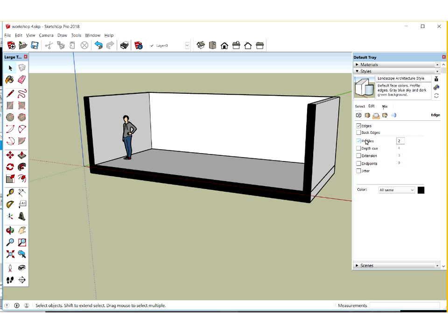With the edges, if profiles are ticked, it'll sort of do a line hierarchy like we do when we draw. It'll have some thicker back edges. So if I untick profiles, it'll make a couple of the edges, some of those back edges, thinner. Now they thicken up again. Now they go a bit thinner again. Okay. Now, what I tend to do with my edges